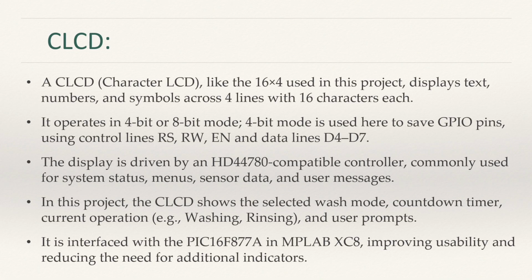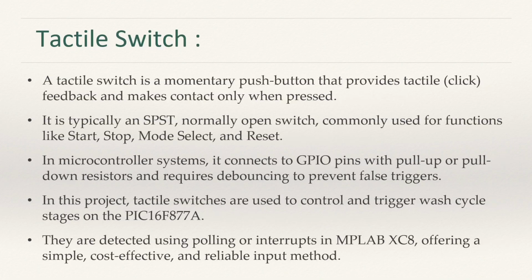In this project, the LCD shows the selected wash mode, countdown timer, current operation, and user prompts. It is interfaced with the PIC16F877A in MPLAB XC8, improving usability and reducing the need for additional indicators.